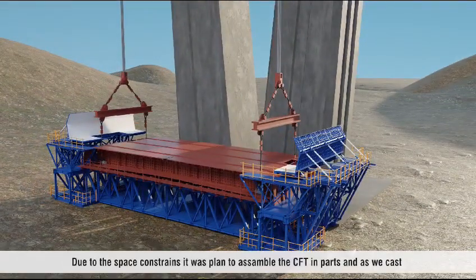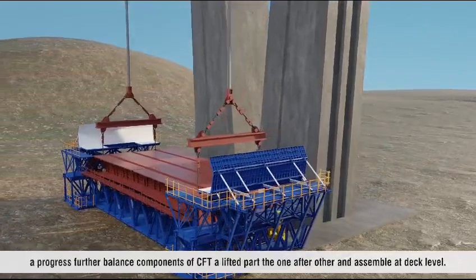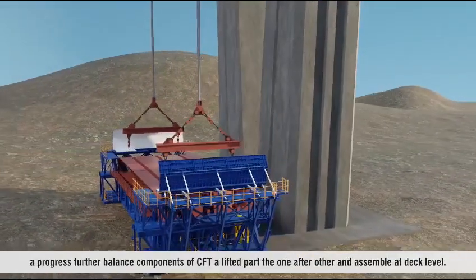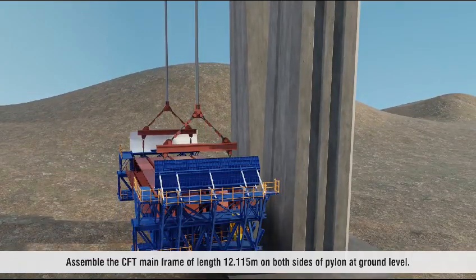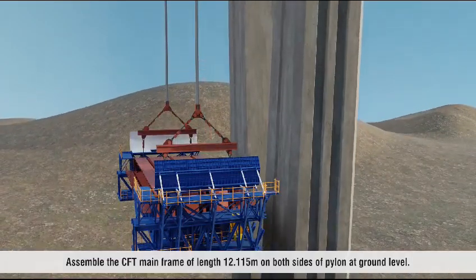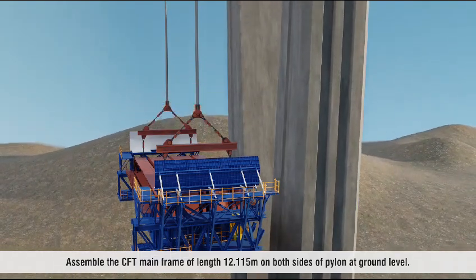Due to the space constraints, it was planned to assemble the CFT in parts, and as we cast and progress further, balanced components of CFT are lifted partly one after other and assembled at deck level. Assemble the CFT main frame of length 12.115 meters on both sides of pylon at ground level.